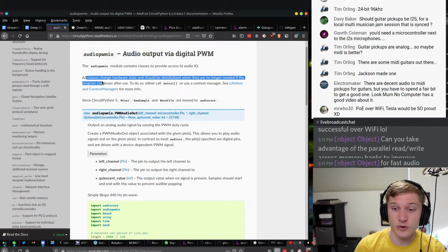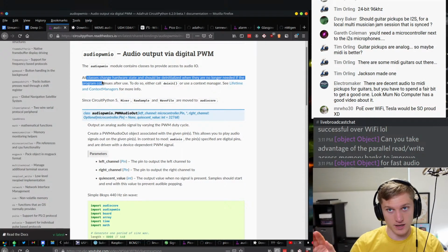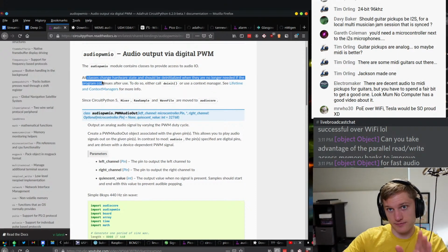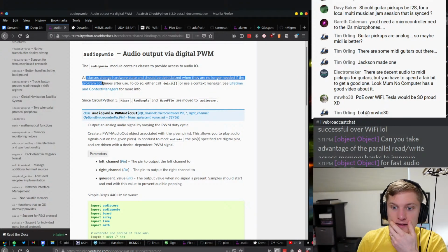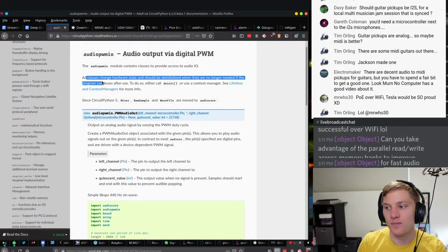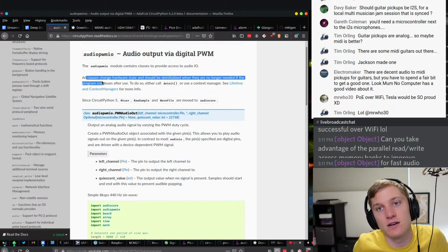So DMA is really cool. I think I mentioned it. DMA is short for direct memory access, maybe. But the general idea is that instead of having a CPU keep track of I'm copying from here to here, with DMA you can say, hey, copy this much stuff from here to here and let me know when you're done. We get some grief in CircuitPython for not being able to do things concurrently. But DMA is something that we take advantage of when we can, and we can do things concurrently as a result.